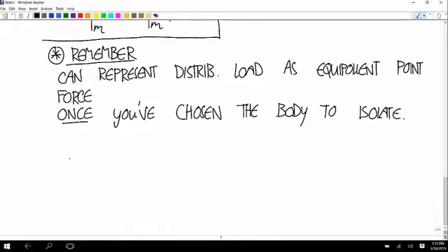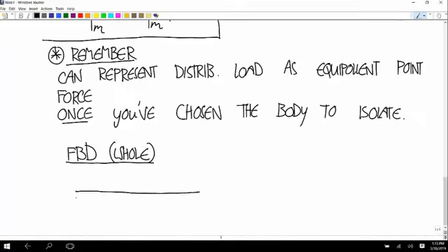All right, so first, external load. So free body diagram of the whole beam we'll start with. So what's acting on this? It's a pin joint at the left. So a pin joint gives you an unknown force vector.